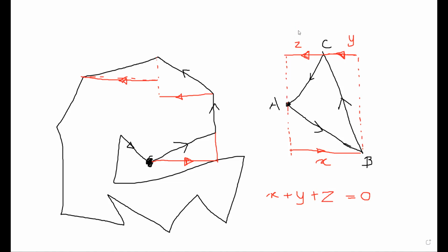So if you conduct the graphical method for this case, then we can have some idea. Let's say we start with A, B, C, D and A. Now you will get an idea where you will stop. In this case, you end up with minus 1. That means 1 millimeter in the west direction.